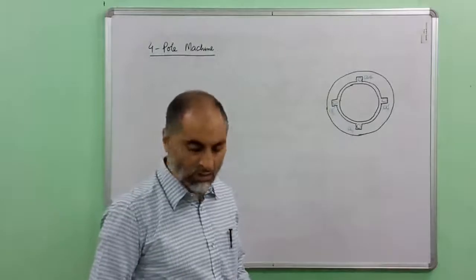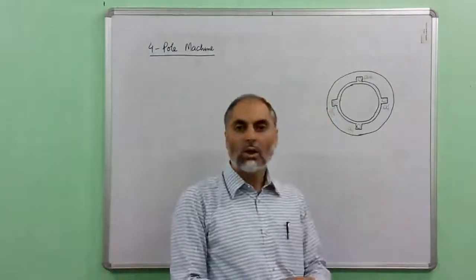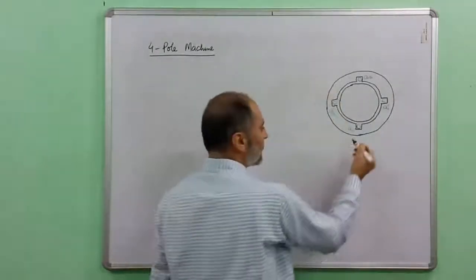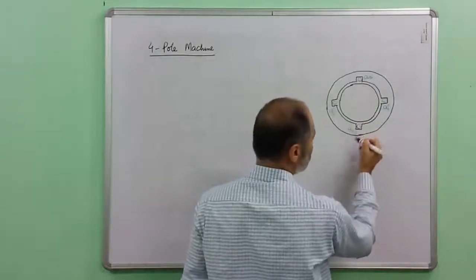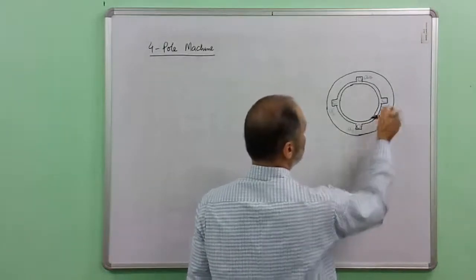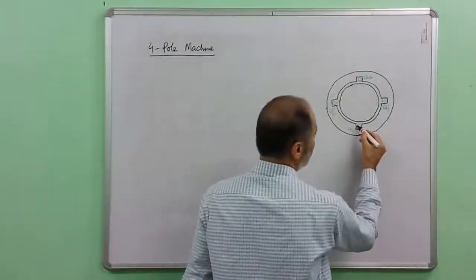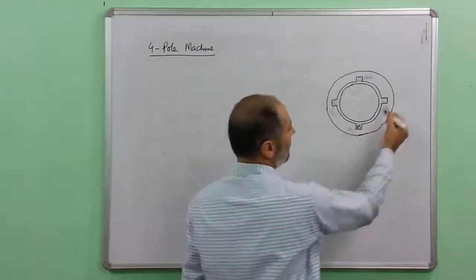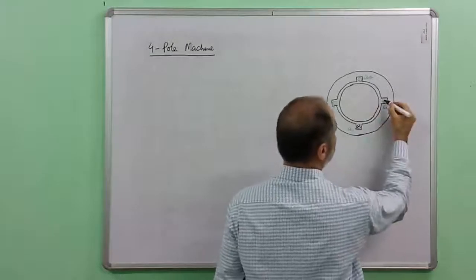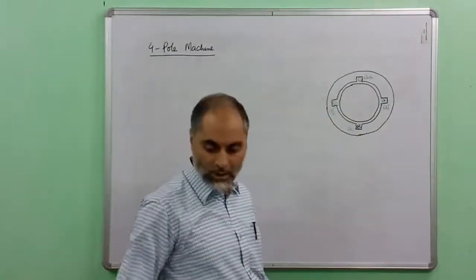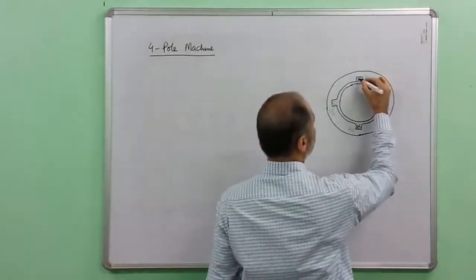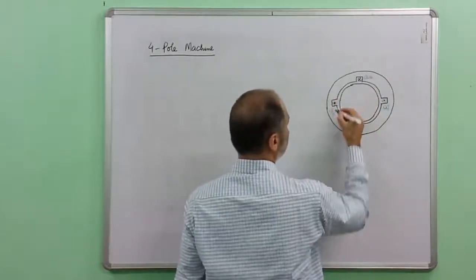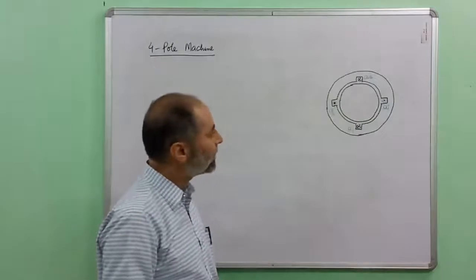Now these coils can either be connected in series or in parallel, so that they together carry a current. Once they are connected to an external circuit, suppose the coils are connected such that the current enters this coil side, you have a cross here, and therefore the current will be coming out at coil side A prime. Similarly, the current will be entering the coil side A2 and the current will be leaving the coil side A2 prime.